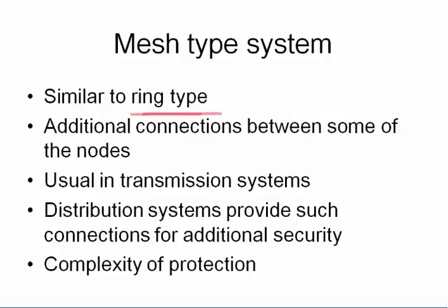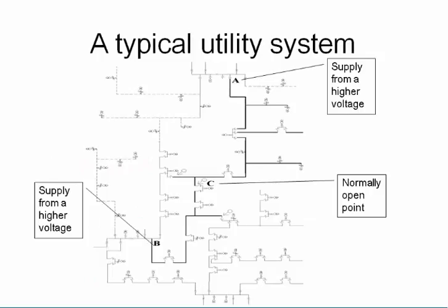Mesh is similar to ring, but it is more complex, used in transmission systems, and protection is quite complex, really complex, used for big cities or transmission systems. So this is a typical mesh where you have different reclosers, circuit breakers, transformers, a complex interconnected jungle which is hard to manage. You need to use expensive automation, protection, communication systems used for transmission of big cities.